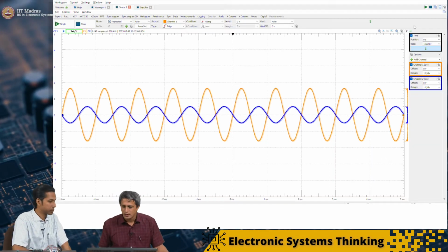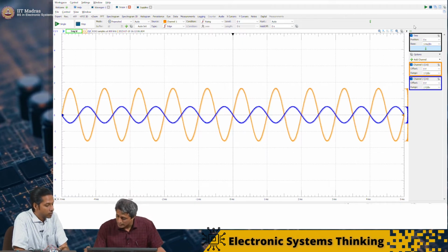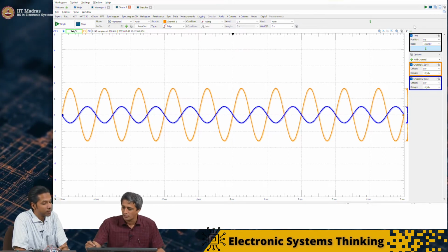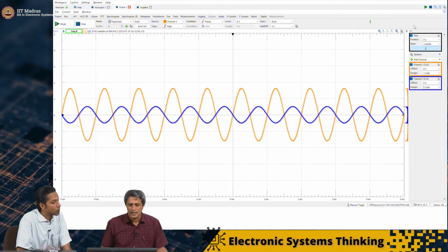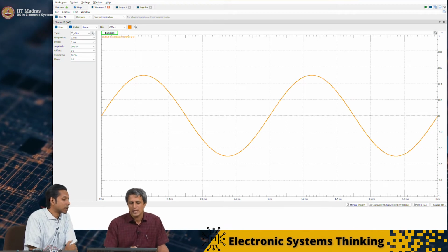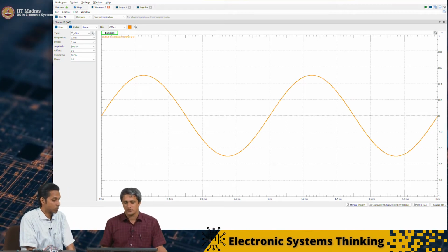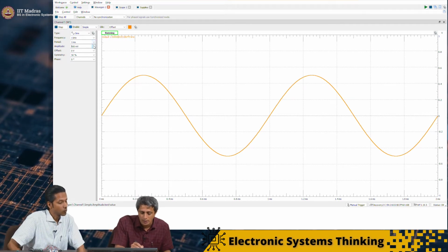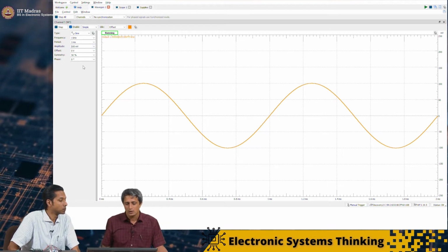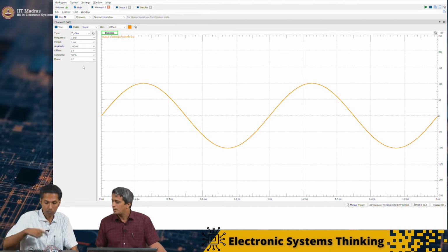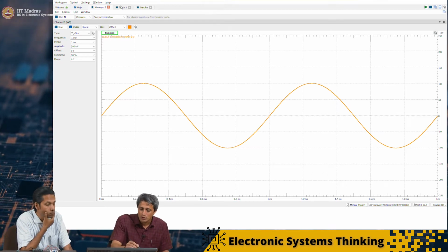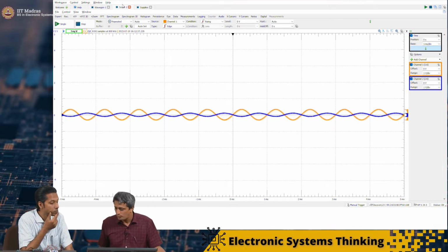What happens now? As usual, we are going to look at this oscilloscope full screen, and a signal generator. We give an input signal which is a sine wave. This is the function generator output. It's 500 millivolt, so maybe I'll make it 100 millivolt, 1 kilohertz input. It is given to the input of the amplifier, and the output we are going to look at on the scope.